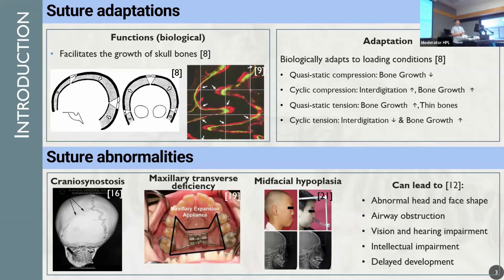Okay, well, I think that's an interesting open question. And also I kind of like shear in the sense that, I can't remember who, was it you or someone who said, it's all about maximizing the surface area. So area by itself doesn't matter, but if you want to make area matter, where's it used? In stress. And so, one thing that interdigitation can do is it helps you spread around the stress. Yeah. And then, when you have more of it, I imagine a lot of that area is in shear direction.